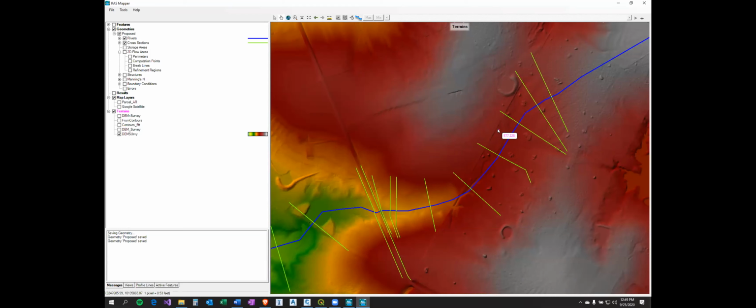But I would say for kind of a legit submittal, I would not go any smaller or any bigger than the 1 meter. If you're going to cut hydraulic cross sections, for hydrology, yeah, you can go bigger. There's nothing wrong with that. But for hydraulic cross sections, I think you'd probably want to preserve that 1 meter resolution. It's a lot slower, and something that Adam brought in, which is we don't have time to watch him process data for 20 minutes. So I get that. I totally understand that. But sorry, I'll shut up, Adam. I'm hijacking. Oh no, that's quite all right. You're technically the expert in this.